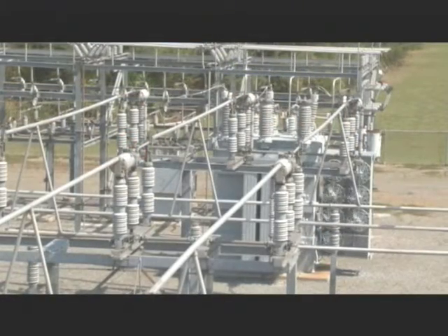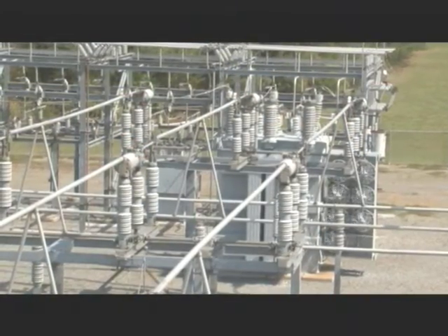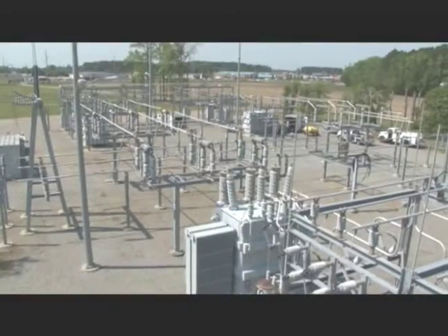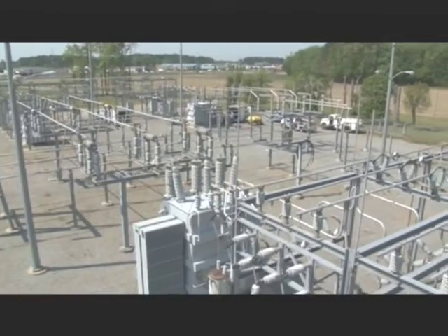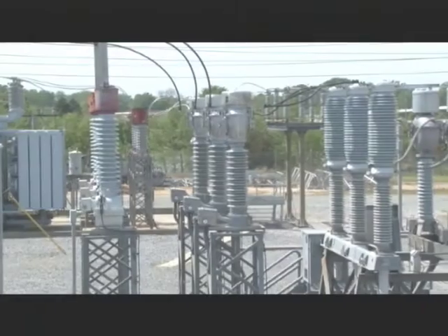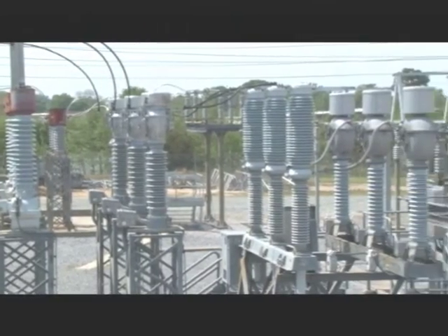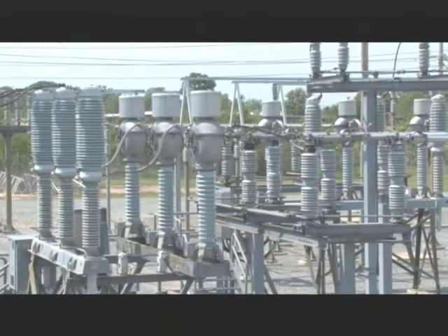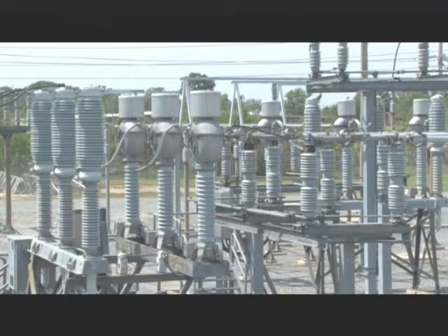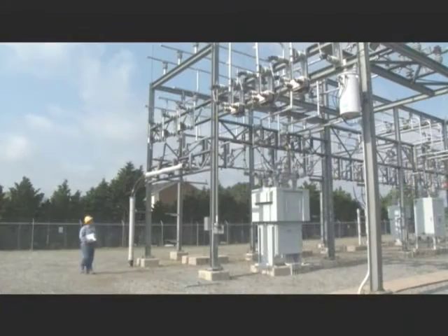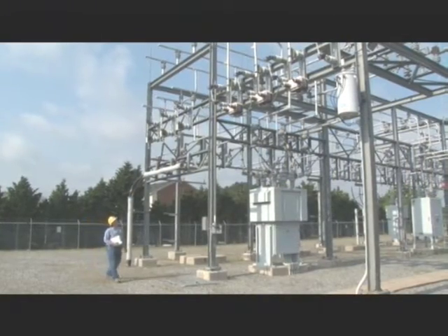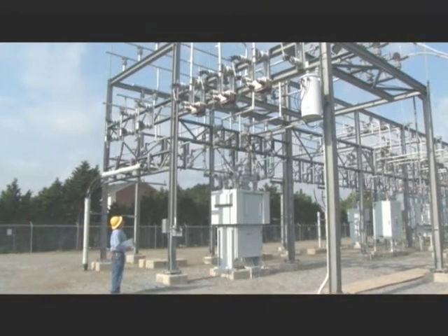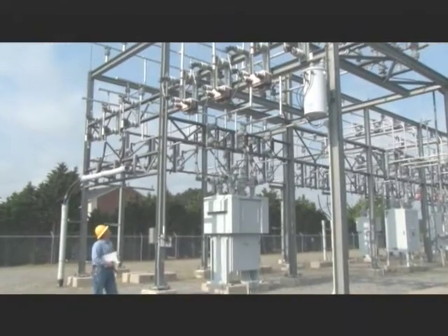At first glance, a typical substation looks like a cluttered, confusing maze of structures, conductors, and other equipment, but once you know what to look for, it's really much simpler than it seems. Where transmission lines enter the station, all of the insulators and bushings on station equipment are relatively large. This is the high voltage side of the substation. Where distribution lines leave the substation, the conductors and poles are also a lot smaller than anything you'd see on the transmission side of the system.